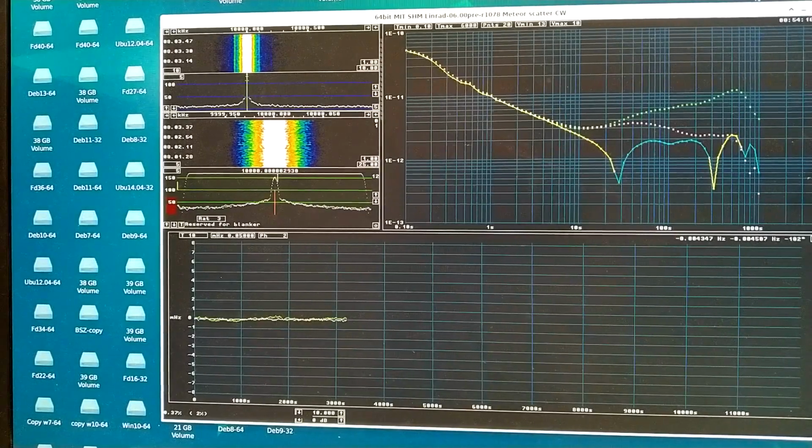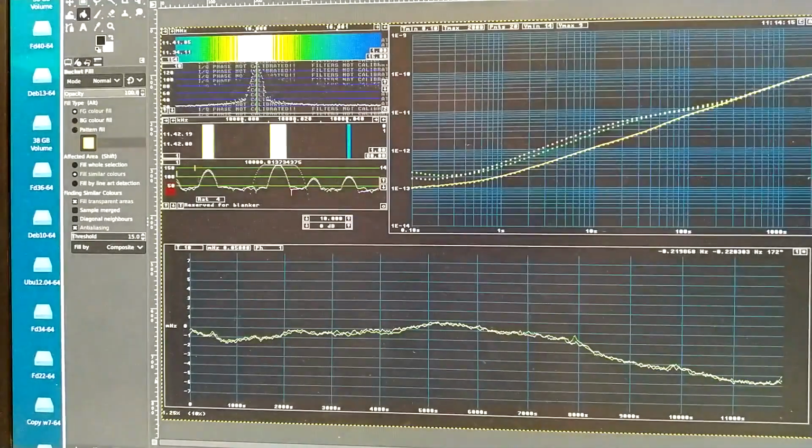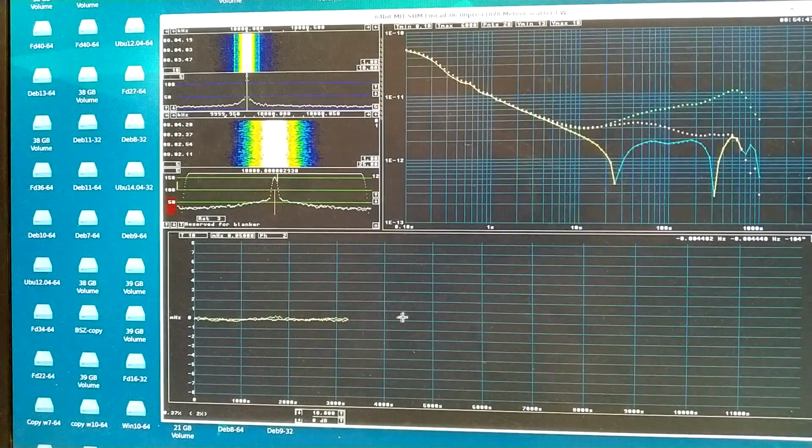I have changed the PLL resistor from 44 kilo ohms to 4.4 kilo ohms. That's a factor of 10. It means that the loop is now much faster, because not only is the time constant 10 times smaller, but the gain in the PLL loop is also higher. I have the same scale as I had previously, and that I had here also. But it seems I could make the locking even a little bit faster.